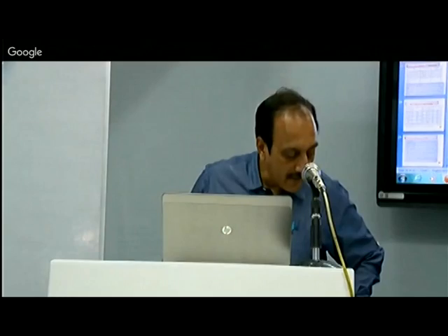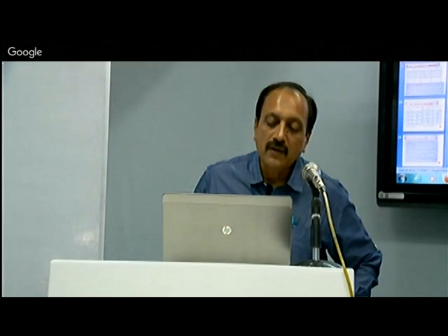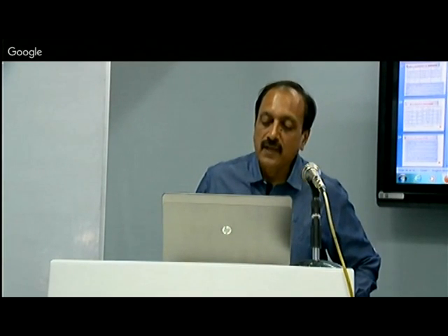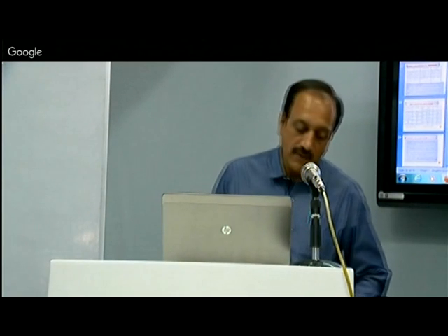अब बहुत बार क्या होता है कि आप मटेरियल को साइट पे ले जाते हैं, आपको वहाँ पे इमीडिएटली कॉम्पैक्शन नहीं होती, so you can allow that to happen, but when you are going to spread it out, you are going to add more water, so you have to make up for the evaporation losses, but a good quality is ensured when you are using a paver.